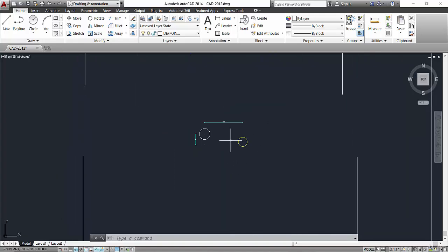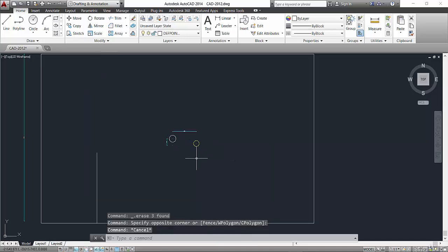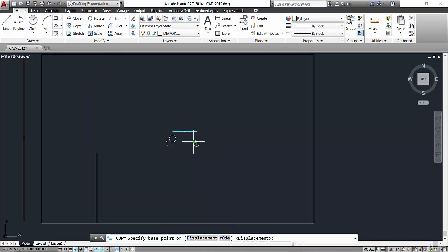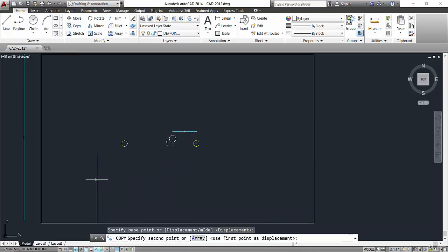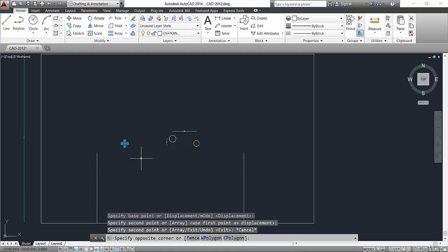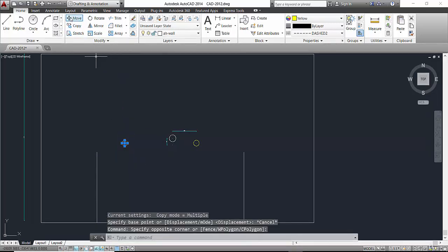Center of rigidity represents the rigidity of the shear wall or the system used for resisting the earthquake. That means if we have a shear wall here, the center of rigidity will be in this place, near the shear wall. If we have a shear wall here, the center of rigidity will move right to here.